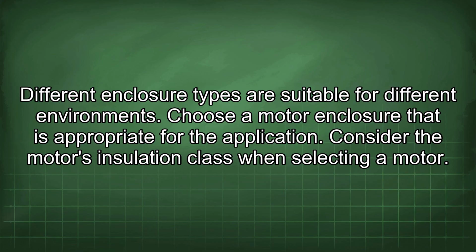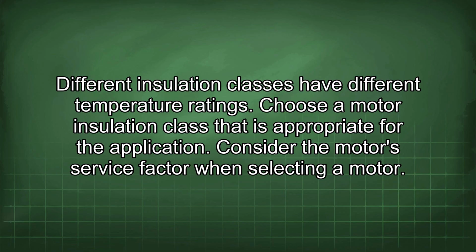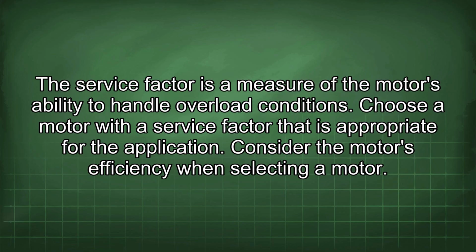Consider the motor's insulation class when selecting a motor. Different insulation classes have different temperature ratings. Choose a motor insulation class that is appropriate for the application. Consider the motor's service factor when selecting a motor. The service factor is a measure of the motor's ability to handle overload conditions. Choose a motor with a service factor that is appropriate for the application.